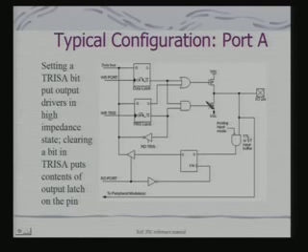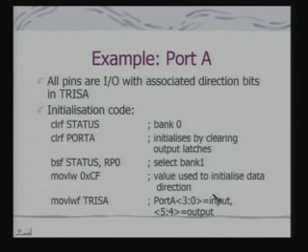When the output drivers are in high impedance state, I can use that pin as an input pin. And in many cases, these digital I/O pins can even be configured to get analog inputs for some other purpose, because these pins are multiplexed to serve the requirements of other peripherals as well. So, this is the basic structure. You can see that these are the two latches which actually record the data as well as the TRIS bit, enabling the direction of operation. Let us look at the code.